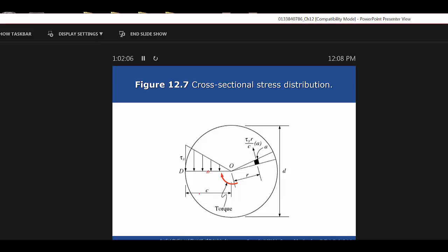Question. So your answer is 55 times 10 to the 6th Newton millimeters, and then they just changed it to kilonewton meters. I thought kilo was 10 to the third. How did it go from 10 to the sixth to kilo? Because it's Newton millimeters, not Newton meters. Oh, yeah, Newton millimeters, sorry. They changed both of them, yeah.